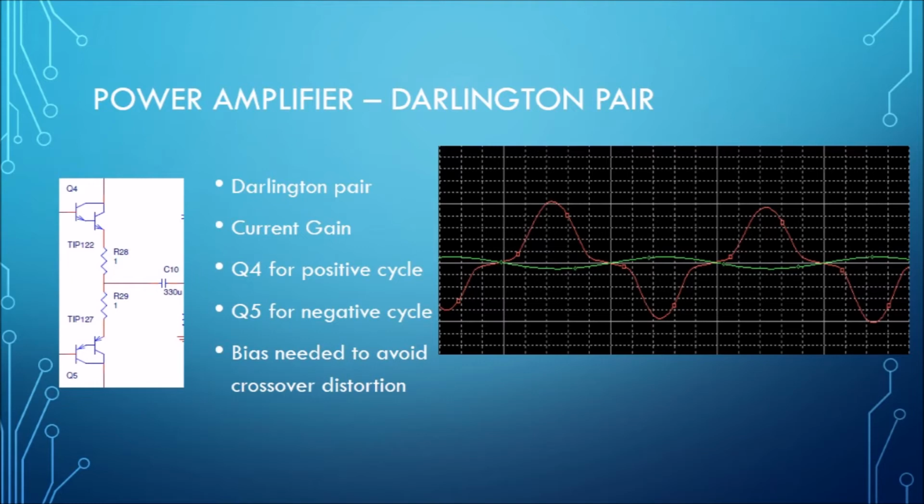Thermal runaway happens when the BJTs heat up and thus let more current, leading to a higher leakage current, which then consequently increases the heat more, which then leads to even more current. And this is a constant cycle that just keeps happening until something in the circuit breaks. Having the degeneration resistors there helps us counter this effect. The penalty that we get because of this is that there's going to be a small increase in the output impedance, but it's still a fairly small output impedance on the order that's less than 8 ohms. So this penalty really becomes not very consequential.